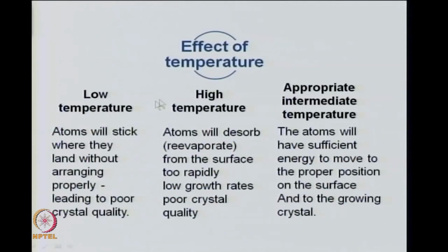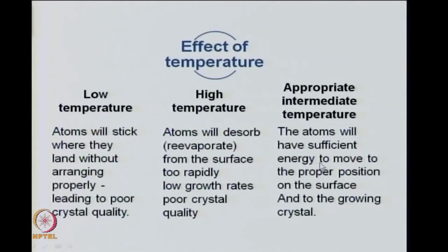The temperature should be sufficient. So, you need an appropriate intermediate temperature, and at that temperature the atoms will have sufficient energy to adsorb and then move to the proper position on the surface, which will lead to the epitaxial layer, and that will be the correct growth of the crystal which you want.